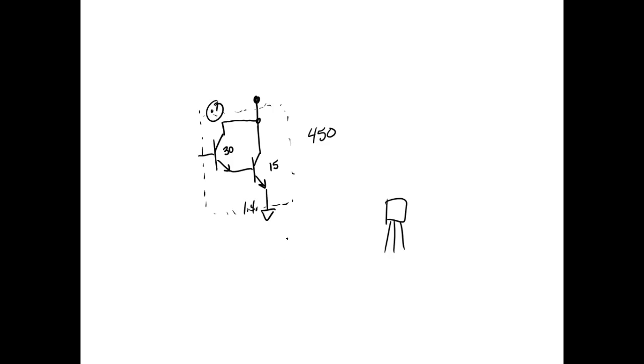And I made this same mistake. I was working on a printer, and the schematics had the thing drawn like that. We were having a problem right in that section, and I was checking it, and it measured that 1.4. Well, it measured more than that. The meter I was using wouldn't put out over 1 volt. These new meters will usually put out enough to break over an LED. The old meters didn't put out over 1 volt on the diode scale, so they wouldn't break over 2 junctions. So I had a good junction up here, and then this junction checked bad, it checked overload.